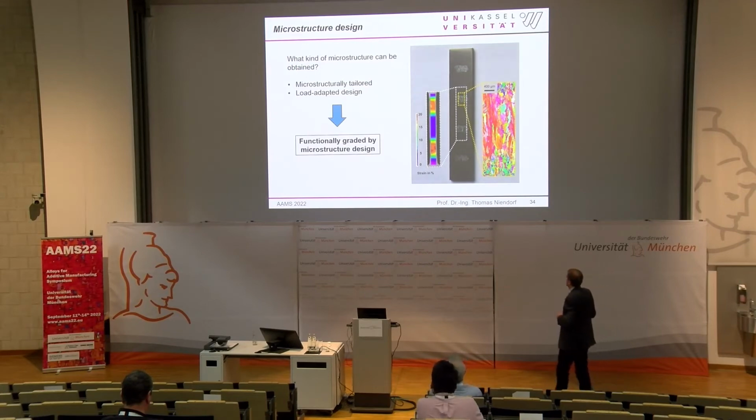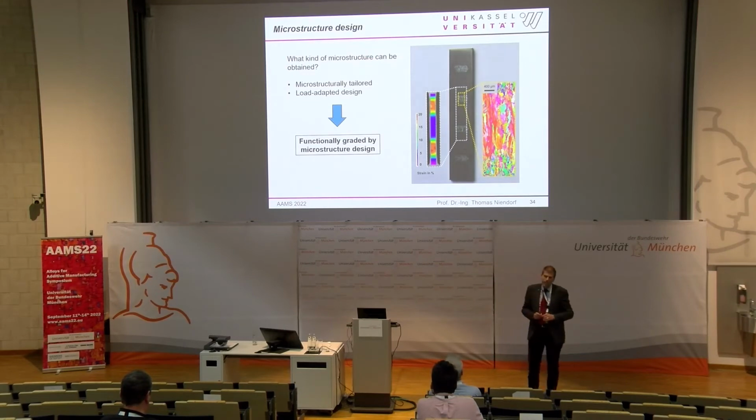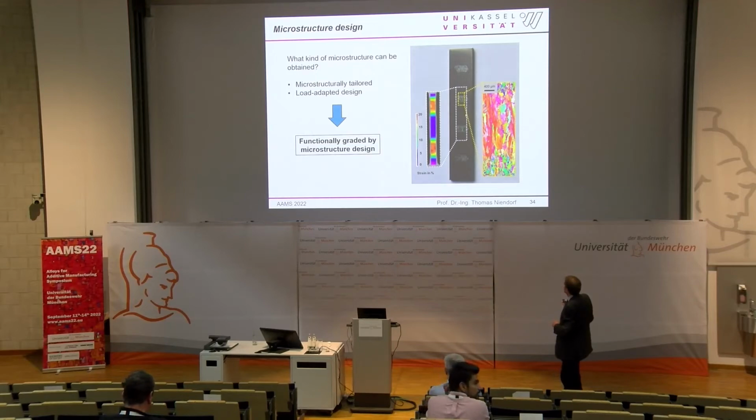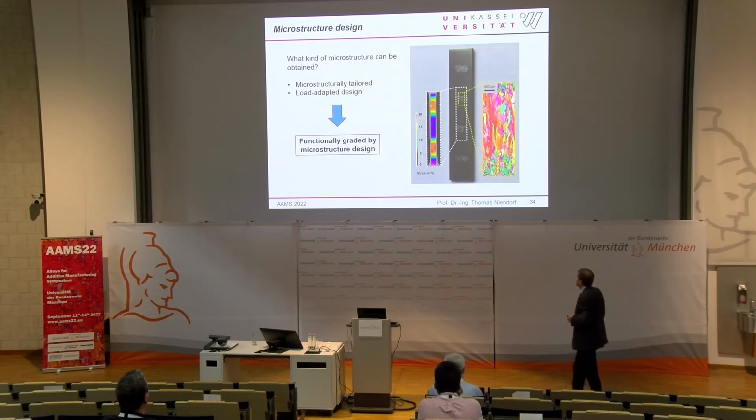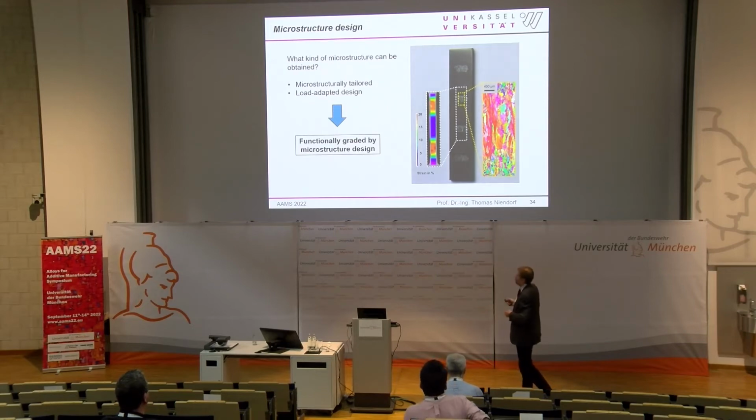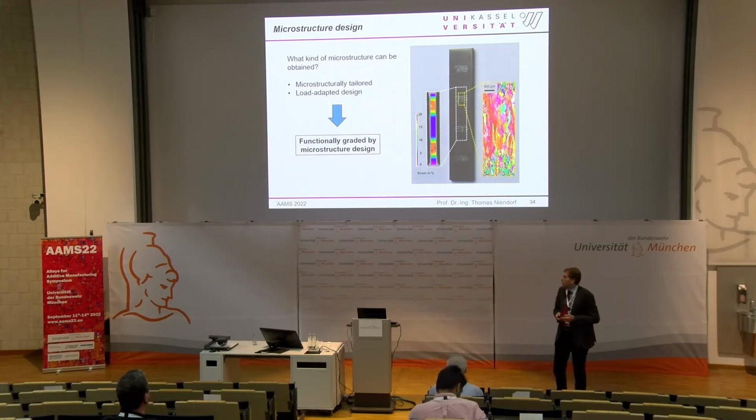So this was done in, I think, 2013. And we used this dual laser SLM system and just switched the laser. So the embedded islands here, this is printed with the kilowatt laser and the surrounding with the 400 watt laser. And we can switch between fine-grained and columnar-grained material, and looking at the mechanical response, we can see that, of course, the coarse-grained parts have lower strength, and so we see much more deformation if we do a tensile test. So this is nothing but results obtained by digital image correlation at that point.